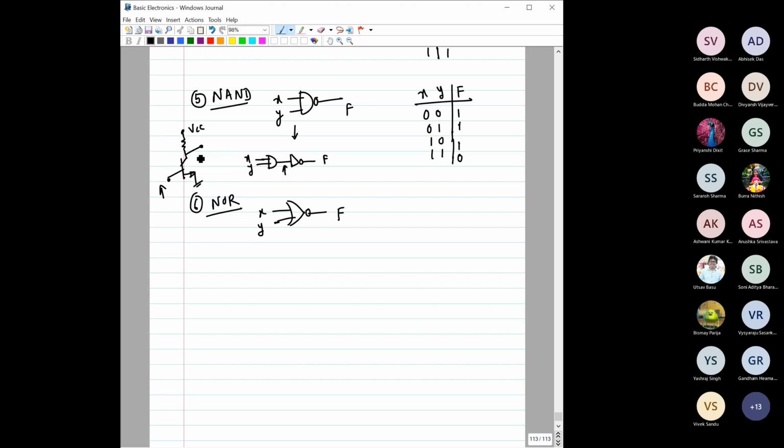When the input is high, this transistor is on, then here the output would be very low, around 0.2 volt. So when this is 5 volt, this is around 0.2 volt. When the base voltage is 0 volt, the output would become 5 volt because the transistor is off. So this is actually an inverter circuit, not that op amp. This is a basic inverter actually.